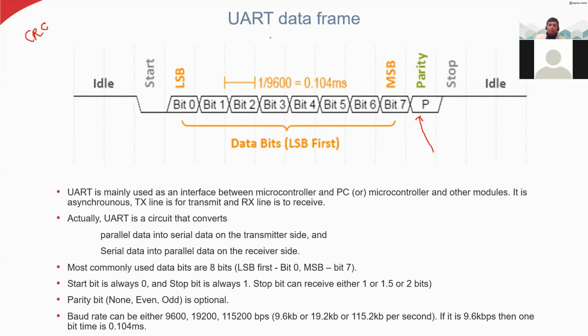When we talk about this UART data frame, maybe it's not going through several networks, but you are just directly connecting the USB cable and transferring from the microcontroller to your PC. But anyway, the logic is the same. So we have the parity check and the data bits, and we must have the start bit and stop bit to differentiate between different frames.